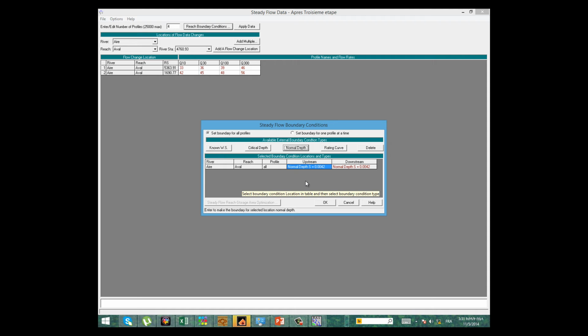Then slowly it becomes wider until the velocity becomes a non-scouring, non-silting velocity. This is very interesting for natural rivers, and nature is intelligent. They are always in balance. Because of this, the slope is always very gentle. That is, the slope itself is a non-scouring and non-silting slope that supports the velocity as well.